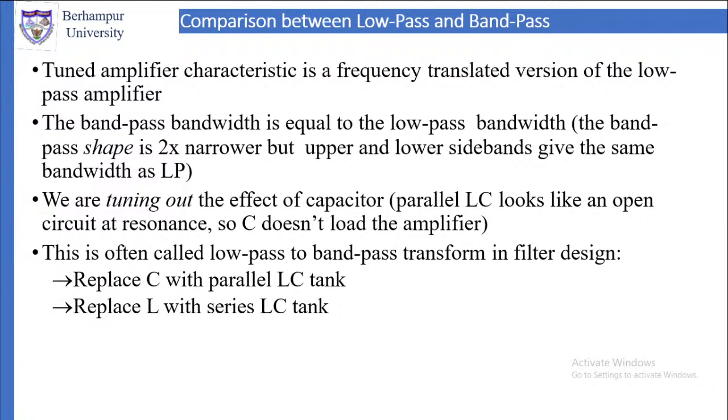This is often called the low pass to band pass transform of filter design. If you read filters in your communication circuits, you will understand this. Replace C with a parallel LC circuit. Replace L with a series LC tank circuit.